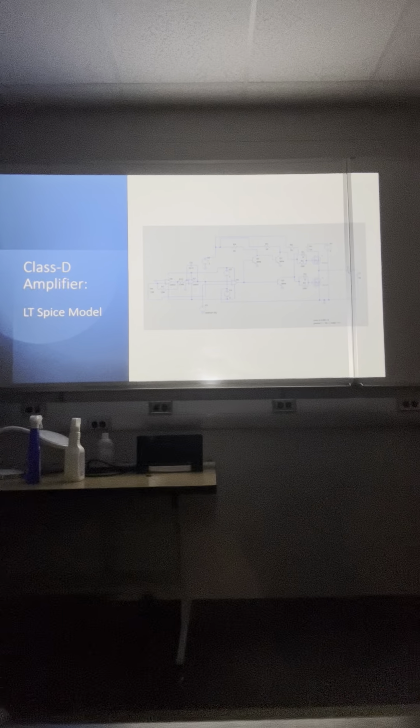Interestingly enough, the library that we were using to interface with this display did not have bars whatsoever. So right above this is a bunch of code for defining bars and how to make a bar. Here we have no bar, bar 1, bar 2, all the way to bar 7, to define how tall the bar is going to be. So in the setup, we just declare our pins. These are the pins that are going to be reading from the actual filters, and then add the characters, the actual bars that we had defined earlier, that way we can display them later on.